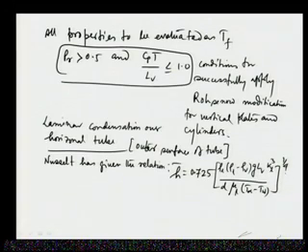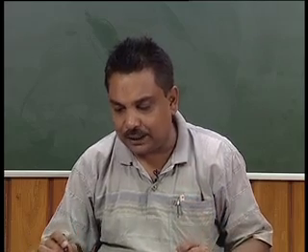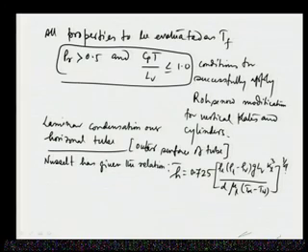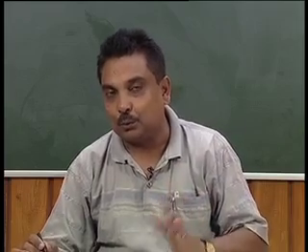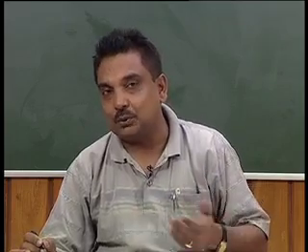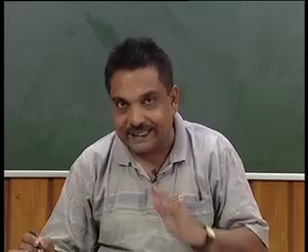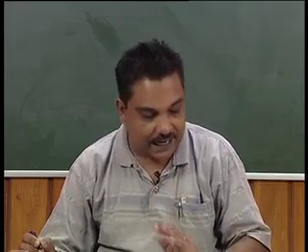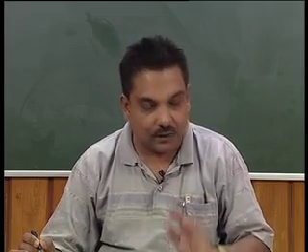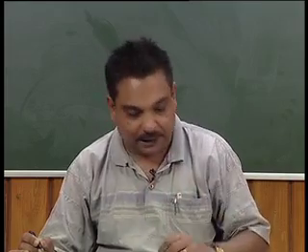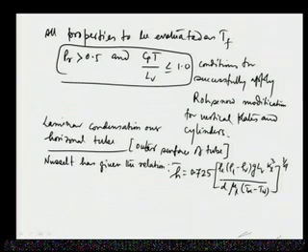Previously it was 0.943 and the coefficient has been changed. L_V is L_V only, it is not L_V dashed, which is proposed by Rosenow, because this is the Nusselt one. If somebody wants to use conditions like cooling of the liquid film and a non-linear temperature profile, then L_V dashed might be used, and L is replaced by diameter.